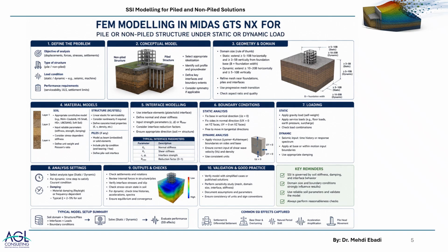But for static ones, you can, as you know, apply point loads, line loads, gravity loads, area loads, those kinds of things. It's important to know which loads to consider and to apply the loads at the stages that they really happen in practice.